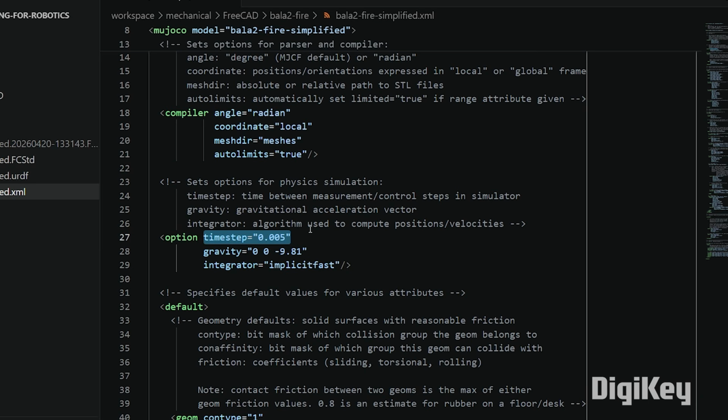So when we go to our PPO algorithm, we must understand that the time steps computed there are also 5 milliseconds. And when we deploy to our firmware, we must ensure that our time steps there are also 5 milliseconds, which means that we take a reading, we perform inference to figure out which action we want to take, and we need to take that action all within 5 milliseconds.